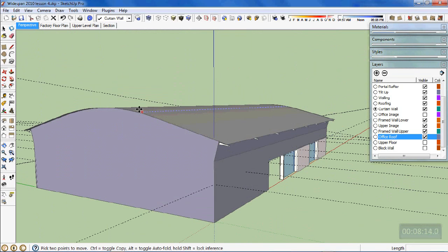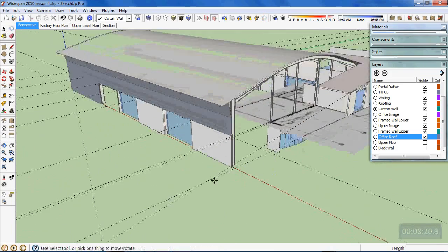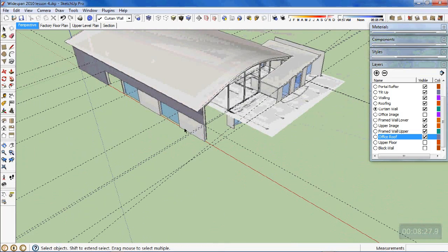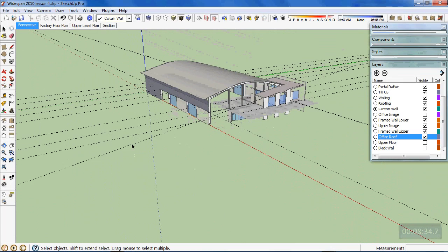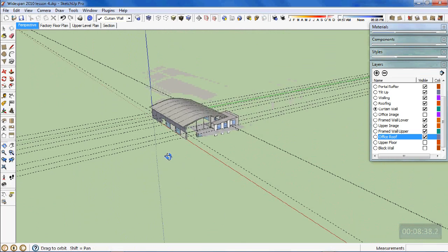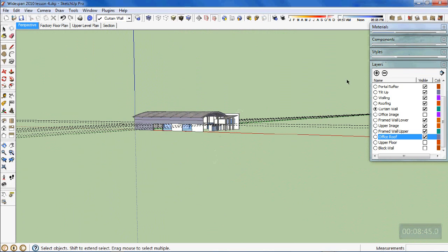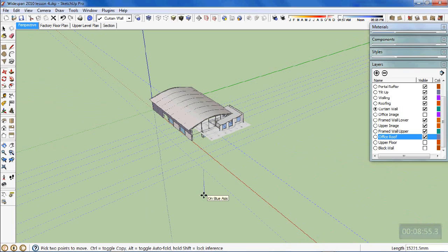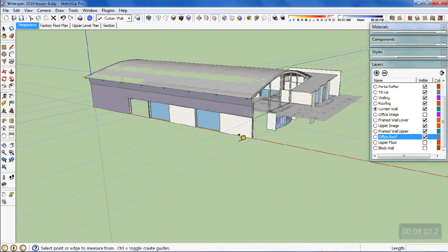Well, it's better if you actually, before you do that, it's better if we actually have that set out line down on the factory floor level. So in view of that, I will get rid of that like I had done. I'm going to put all of my set out lines back down on the factory floor line now, because it's easiest just to select them all in one go. Easiest way of selecting your set out lines is to hover into an area like this, and outside your building put a crossing window which will pick up all your set out lines, and then I'm moving them down on the blue axis, the 3300, and then it's simply a matter of giving yourself a construction line that is 280 off the front, because that will be the front surface of the wall.